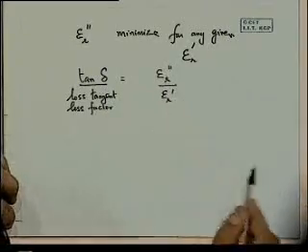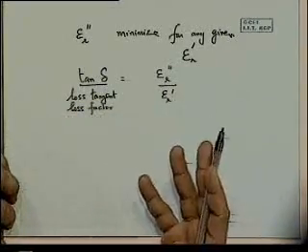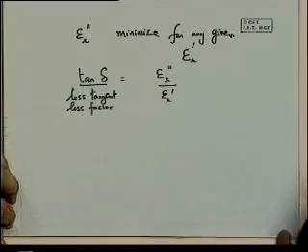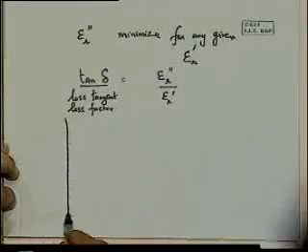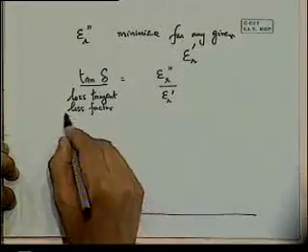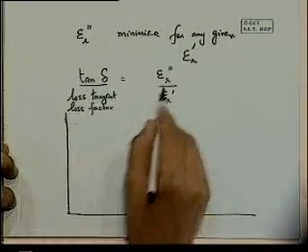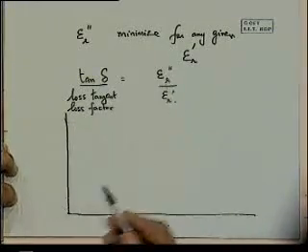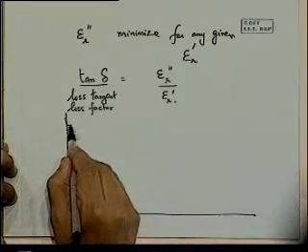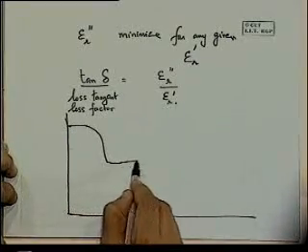These ideas in general apply to each of the different mechanisms that we saw, namely electronic, ionic, interfacial and orientational, and they contribute at different frequencies. So if you plot the real and the imaginary components, both of those as a function of frequency, this is what we will see. What we are plotting is each of them individually, epsilon r prime and epsilon r double prime. You'll see something like this, a series...